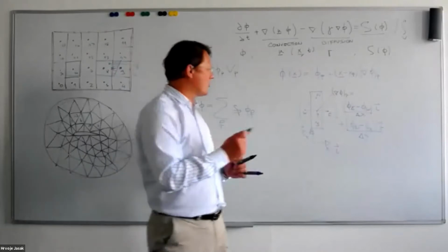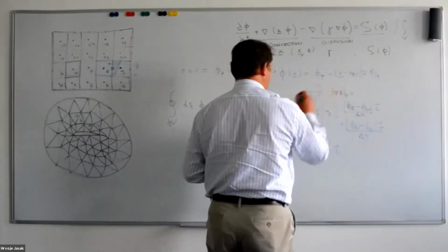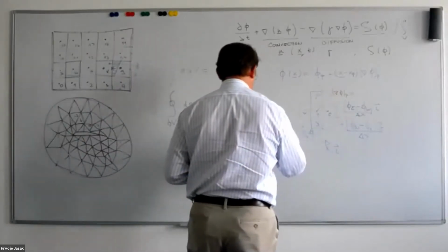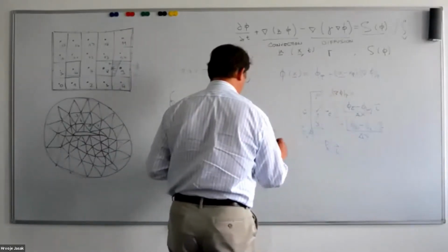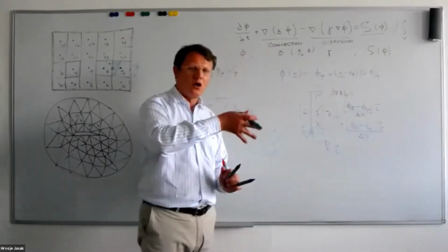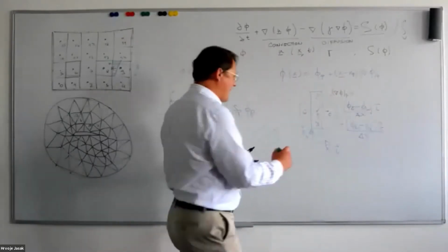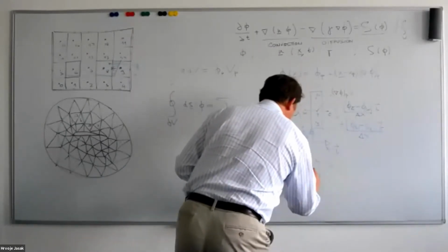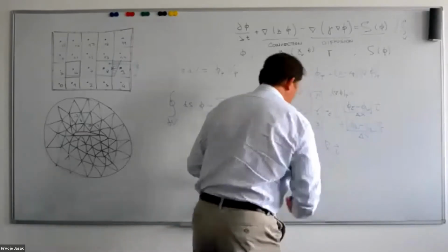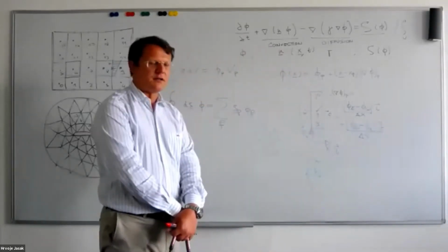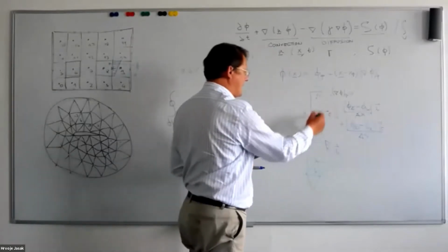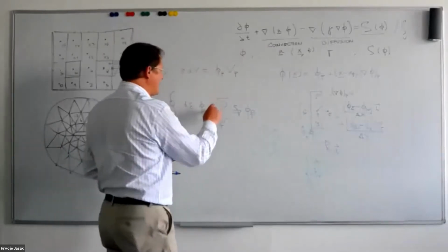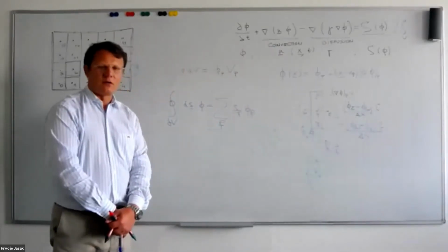The first complication comes if the coordinate system of my east, west, north, south stencil is not aligned with the global Cartesian system. And here I can do some tricks like coordinate transformation. By jumping into a triangular mesh, all of these games become much more difficult. In a triangular mesh, as you can see, there is no such thing as east, west, north, and south, and I can resort to the basic formulation of the Gauss theorem.